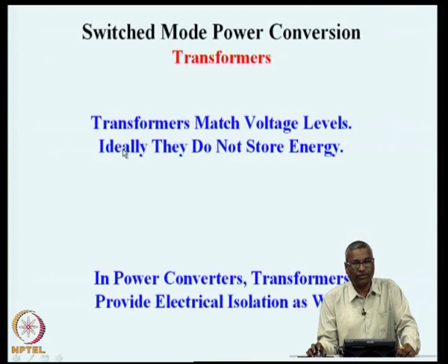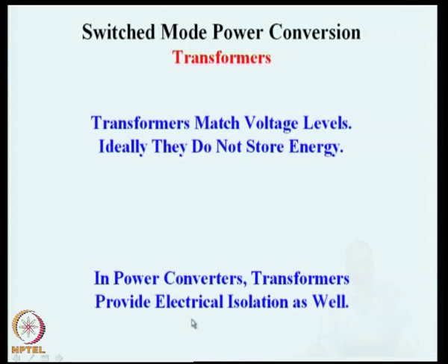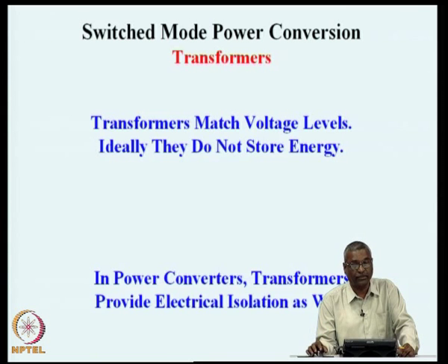In comparison with the inductor, the transformer is also an electromagnetic circuit, but the fundamental difference is that they do not store energy. Ideally, the transformers do not store energy. In power converters, transformers are also used for another purpose, and that purpose is to provide electrical isolation between one part of the circuit and another part of the circuit. If you wish to transfer energy from one part of the circuit which is electrically isolated from another part of the circuit, transformers are absolutely essential in such situations.